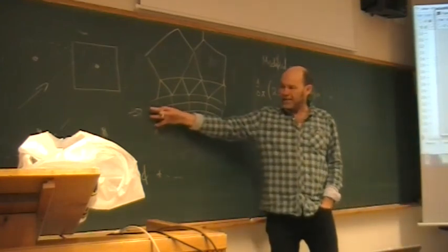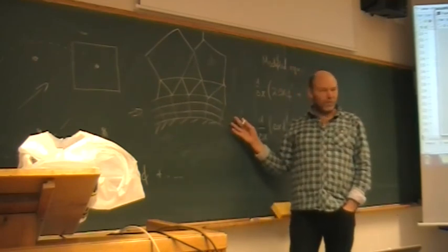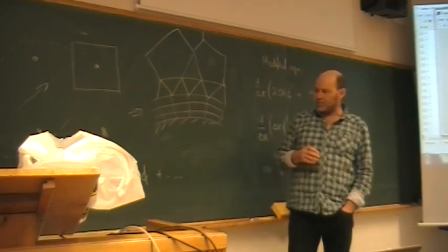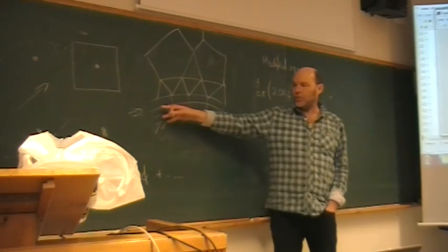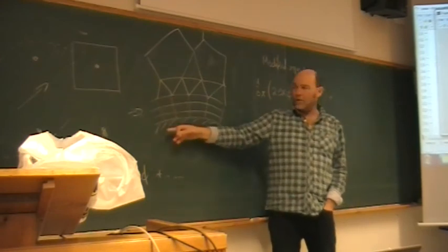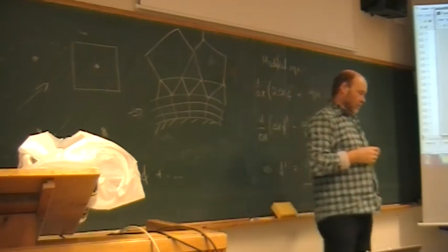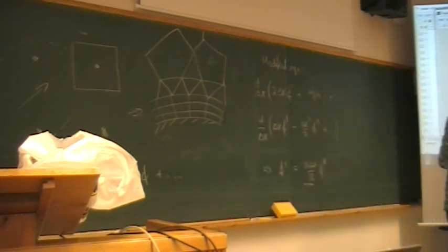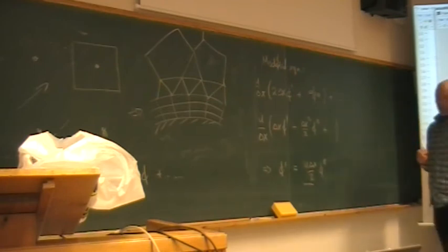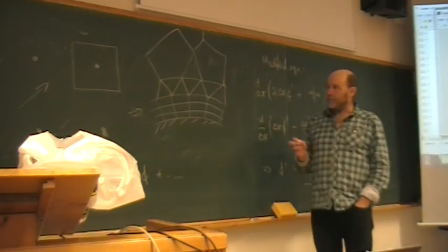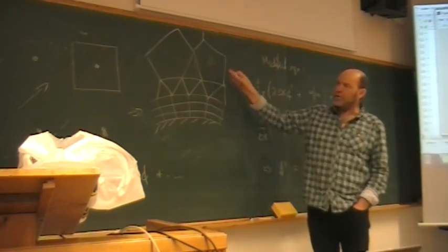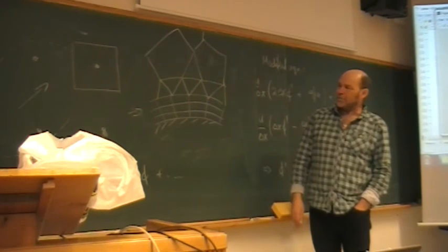But clearly, a rectangular cell system, structured mesh system, is much faster to solve, easier to program. This system here is tricky, messy, you need a lot of bookkeeping. Typically here you will use pointers to find out where you are inside your matrices for all the unknowns. Can be really messy.